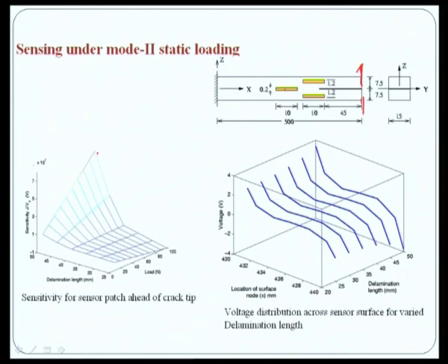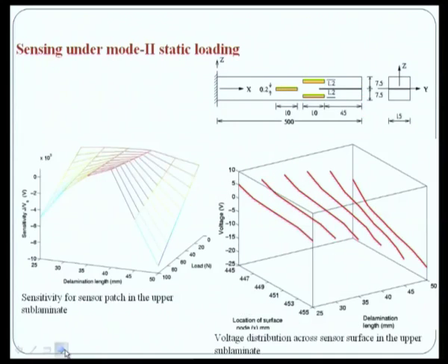So, we can actually generate a lot of these curves and correlate our fracture parameters with the sensor voltage. This is basically the voltage distribution across the sensor surface for a given delamination length. We see that it increases tremendously as the length of the delamination is increased. So, we have shown that we can basically use this concept of sensing using piezoelectric for structural health monitoring applications. We can again do this for a variety of other applications.